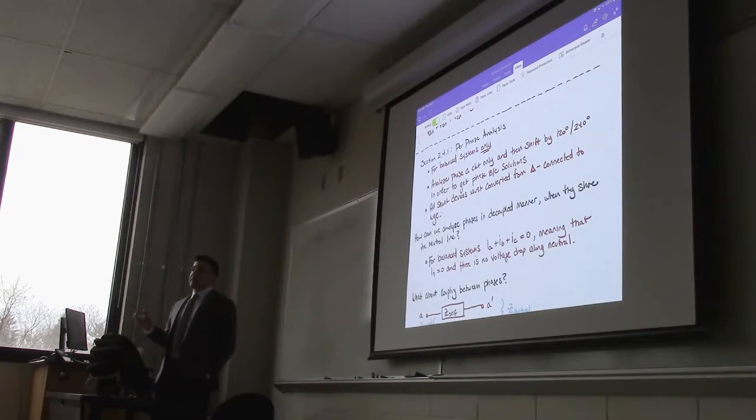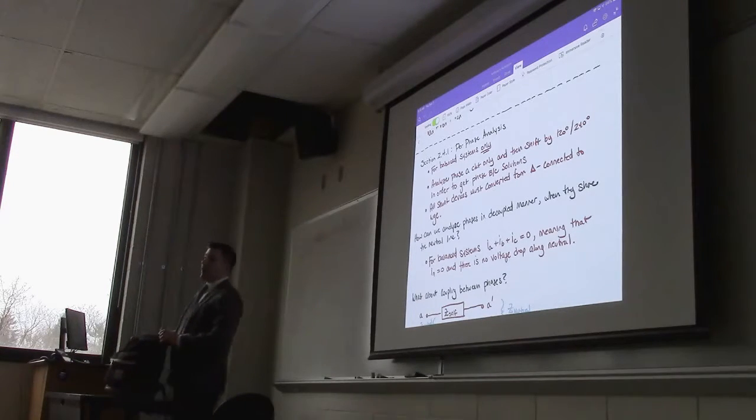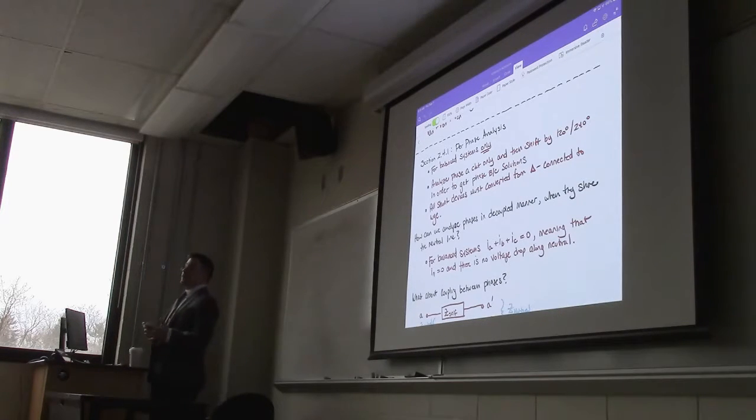Calculating or solving that system in a three-phase form is going to be more difficult than a single-phase system would be. And that's just obvious, right? You have three of everything. However, there's a shortcut. If we can assume that the system's balanced, we can use what's called per-phase analysis, right?